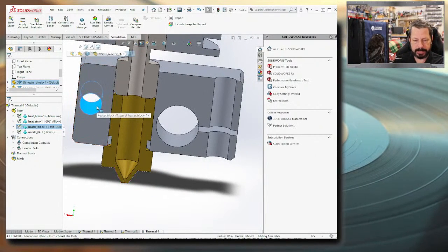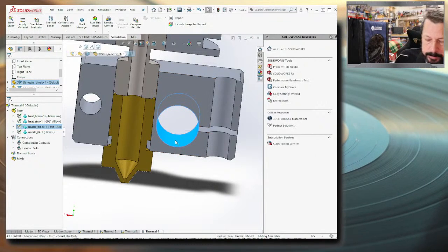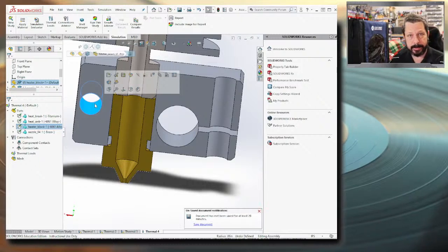So I'm measuring the heat on this side, and I am applying the heat on the other side. And so if anything gets out of whack, then I either apply more heat through the heater, or I apply less heat through the heater. So I increase or decrease the amount of heat coming out of the heater based on what the thermistor is reading and whatever algorithm and tuning that I have set up.